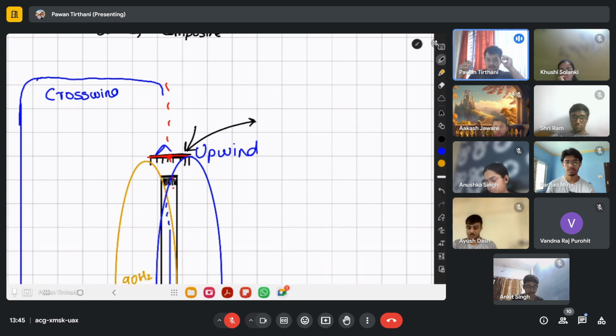So the navigation antenna on board the aircraft also has to be horizontal. Sriram, the same thing that I was, actually you weren't there in the RT class. Any navigation antenna that is there in your aircraft is a horizontal antenna. Okay. Now the question is, how is the localizer giving me horizontal guidance?